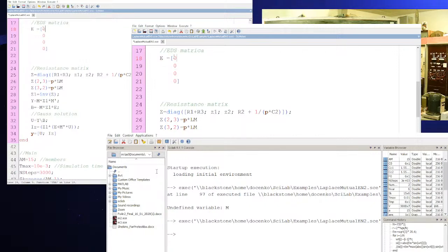I need to represent the energy of the magnetic field of the self-inductance of this coil. Current was flowing before. And if current flowed before, the magnetic field of the coil stores energy. I need it back from 0 plus. You understand?